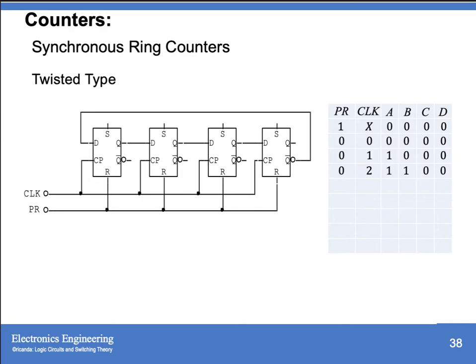The previous value of A will go to B, B to C, then C to D. Third clock pulse, the previous value of D is 0, but since it is connected to your Q bar, the value going to your A is 1. So therefore, we now have 1, 1, 1, 0. At the fourth clock pulse, they are all 1 in your A, B, C, and D.